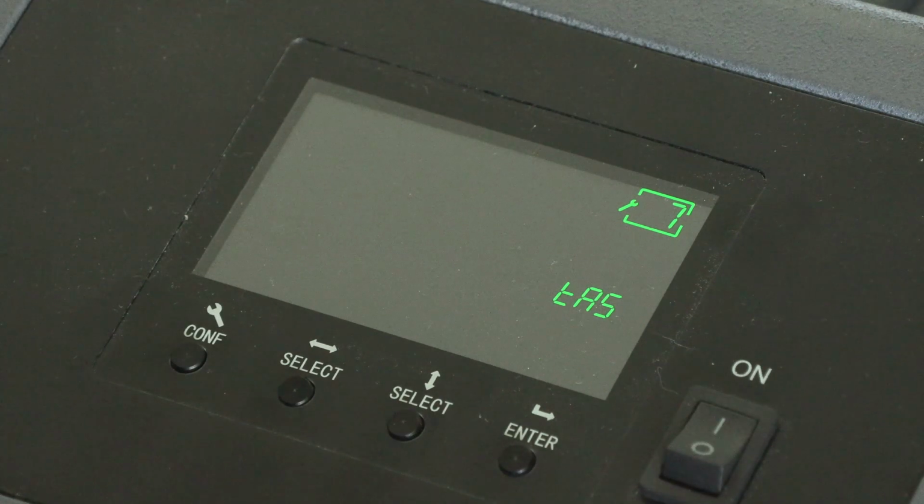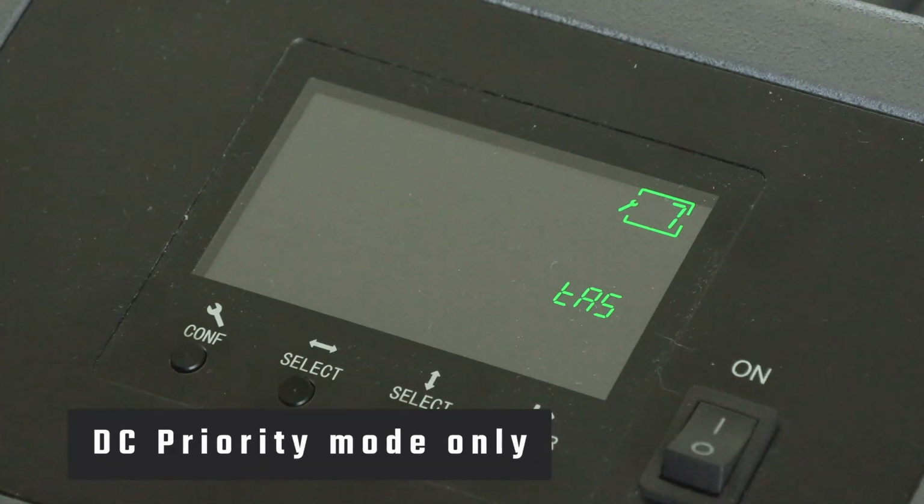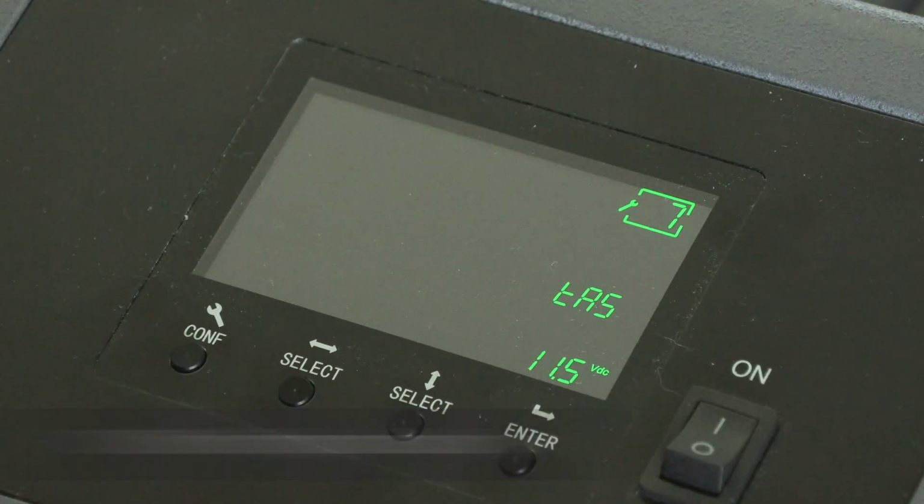Menu 7 sets your DC conversion voltage point. This is used for DC priority mode only, and it sets the voltage per cell in which your unit will switch back to grid.